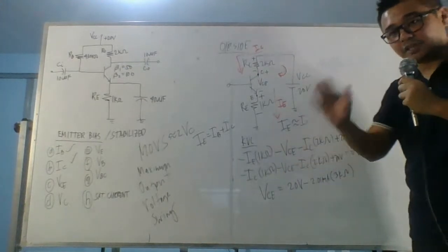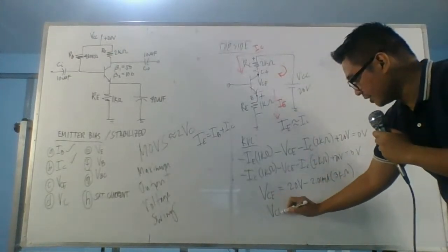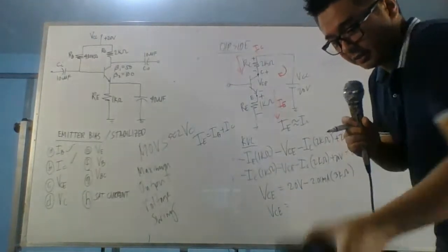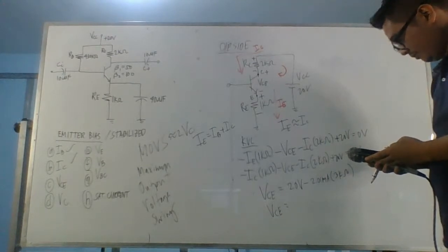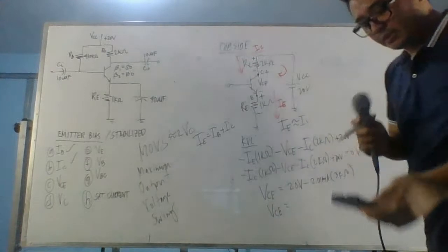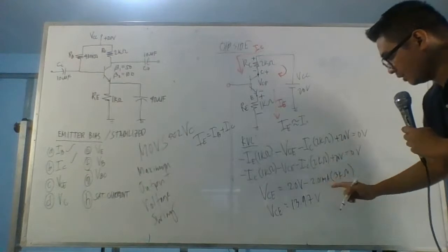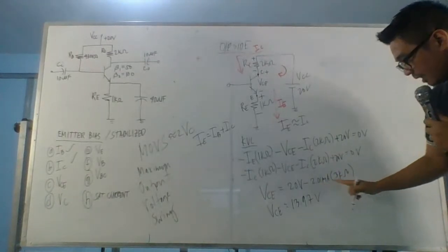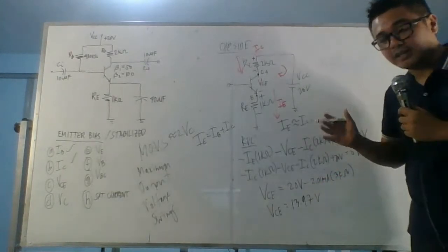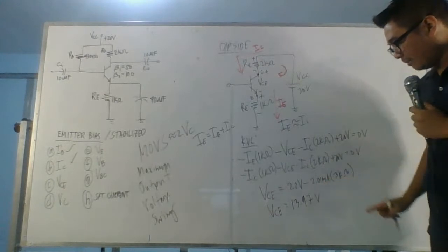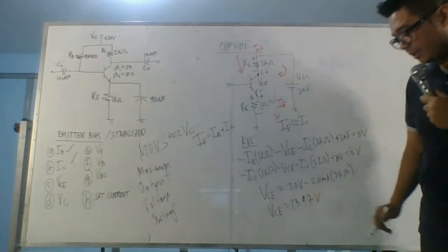So, if you have any questions, just post it in our chat. Next. So, let's solve for this one. Ika-calculate ko lang. So, we have 13.97 volts. As you notice dito, milliamperes times kilo ohms. Pwede na natin direct i-multiply yung 2.01 tsaka yung 3. It's because ang unit natin ay naka-milliamperes at naka-kilo ohms. So, ang sagot dyan, naka-volts. Alright? So, this is your VCE.